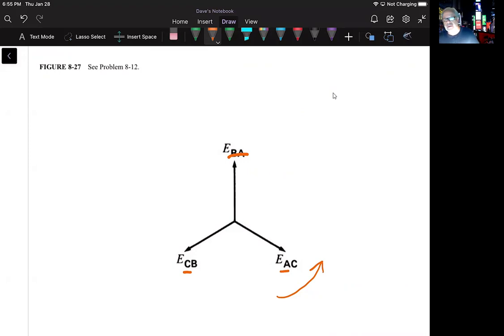Now, when we get into power systems, we talk about synchronizing large generators and how you have to know the phase sequence, because you can actually set up potential differences inside the machine. Potential differences can cause severe damage to these things. And as you go through the rest of this, there are devices. We used to make them. Now they have specific digital devices that can tell you the phase sequence, so you know it in advance.